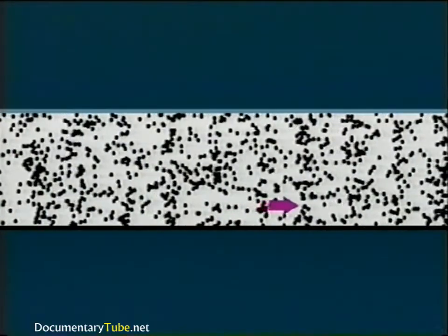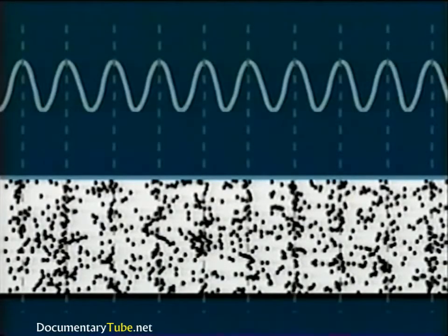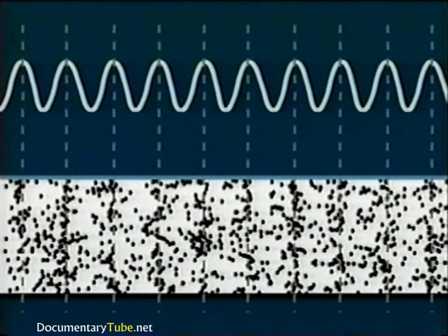The particles themselves are just oscillating back and forth, but it can be seen that the sound waves are propagating outward. As the air particles bunch up, this forms a high positive amplitude area, and when they are most spread apart, this forms an area of high negative amplitude. In their undisturbed configurations, the particles represent an area of zero amplitude. The amplitudes correspond to a change in pressure from its ambient value. This is termed the acoustic pressure. A sine wave is again shown to better understand the wave parameters. Notice how the darker areas of the acoustic wave line up with the peaks of the sine wave.